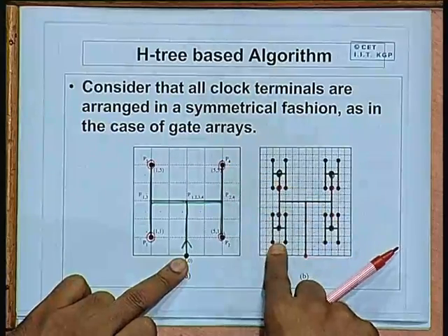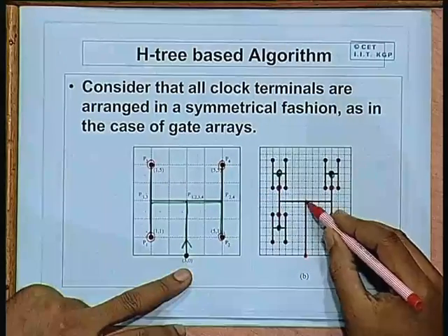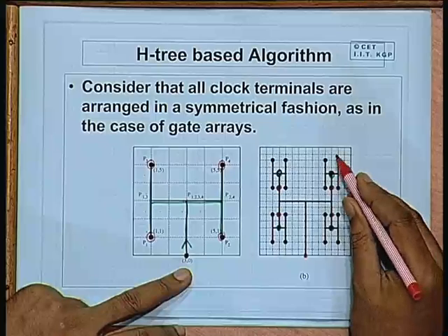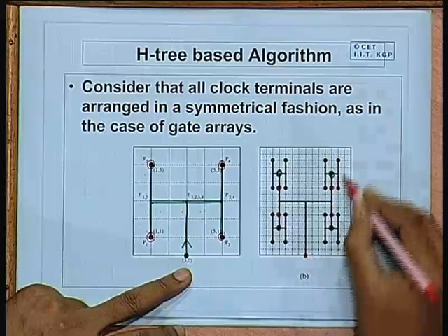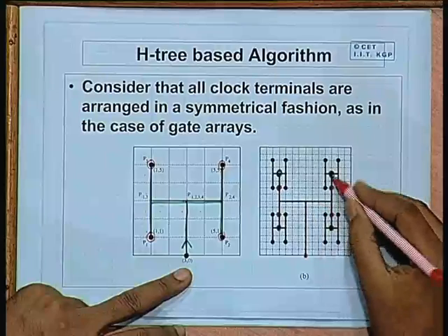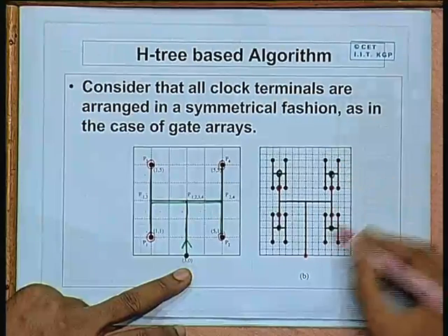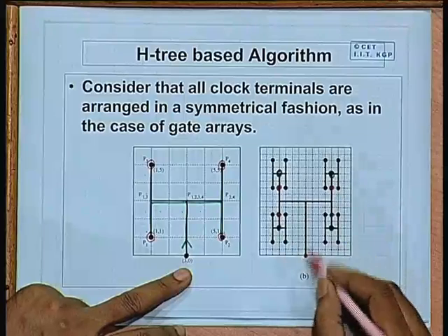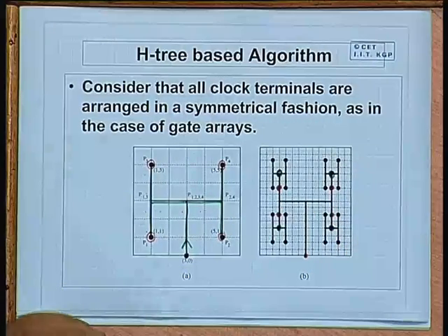So if we assume that the clock routing net will consist of only horizontal and vertical line segments, this is the shortest distance, because these are all Manhattan distances. From this to the farthest pin, you cannot have any net which is smaller than this. Coming back, you could have a shorter one, but in order to have that equal length limitation, we have laid it out like this. Okay.